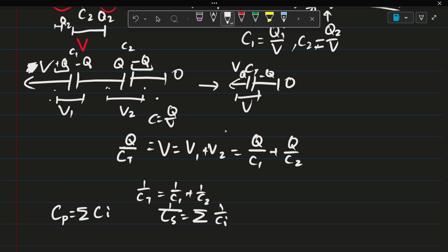But what it does increase is its working voltage. If I have a working voltage of, I don't know, let's say 5 volts and then another 5 volts, but now it is separated between these two capacitors, meaning that our equivalent capacitance has a working voltage of about 10 volts. So this could be useful when you have limited resources and you really require a high working voltage. So this is the way for you to actually increase this working voltage.